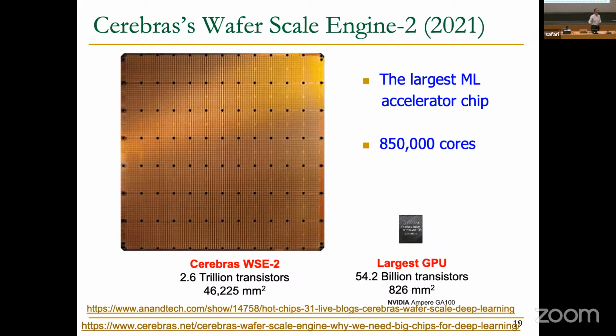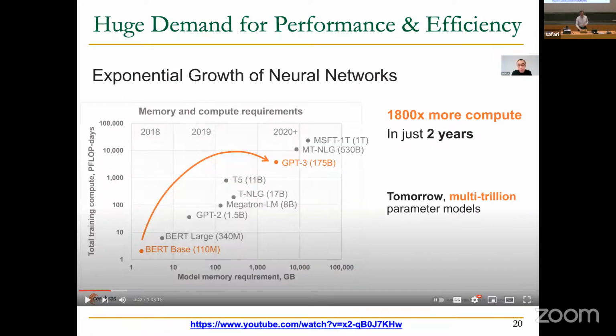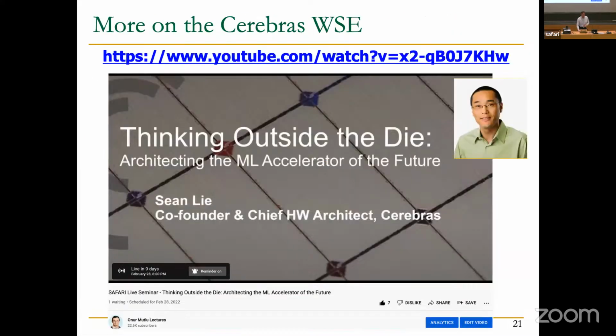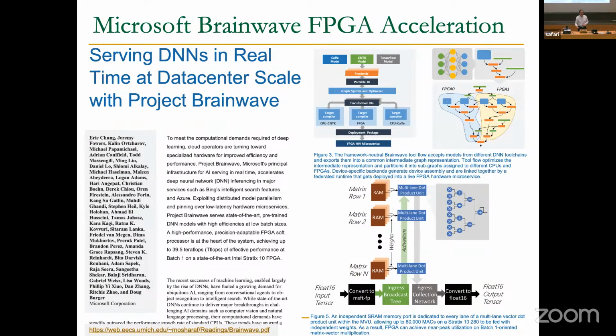This has many processors inside, and each processor is a SIMD processor internally, and they communicate with each other. So it actually consists of multiple paradigms. It's a multiprocessor of SIMD processors or vector processors, if you will. And this is designed as a wafer scale chip, and there are lots of units over here, according to Cerebras, 850,000 cores. And this has large amounts of on-chip memory, 40 gigabytes of SRAM on top of the chip. So they're putting large amounts of computation and memory together. But this is a different approach, clearly, compared to systolic arrays. And you can learn more about this in this talk that was delivered by the CEO or CTO of that company.